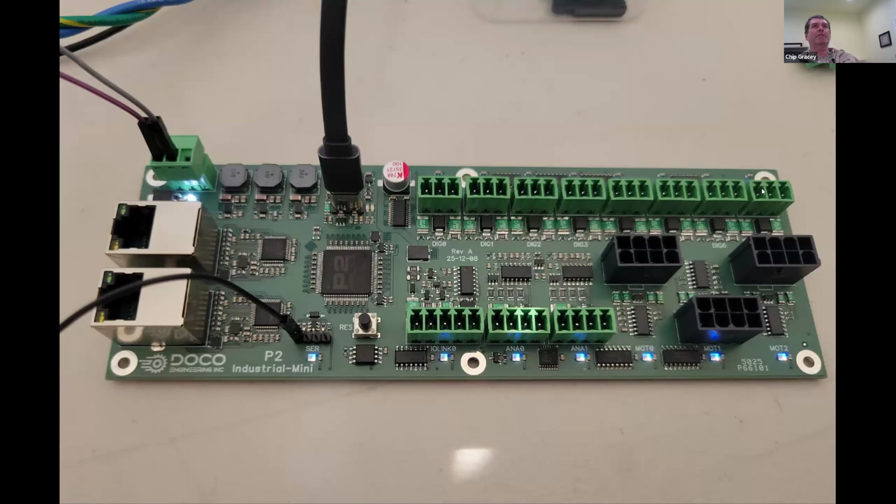These up here are 24 volt digital inputs, outputs. So that's wired 24 volts, ground, and then the IO. And the IO can be biased high or low if you want to connect up PNP or NPN sensors. Or you can also drive. See this little chip right here with this big power supply cap? That's an octal half bridge. So each one of those bridges goes to one of these 8 connectors.